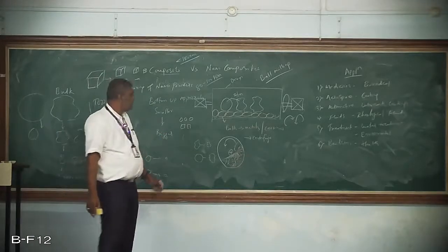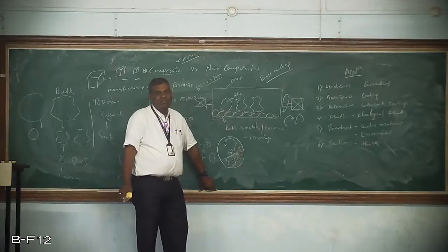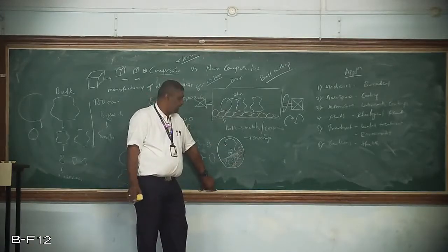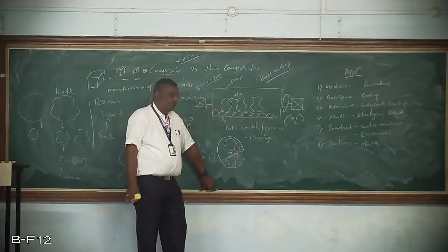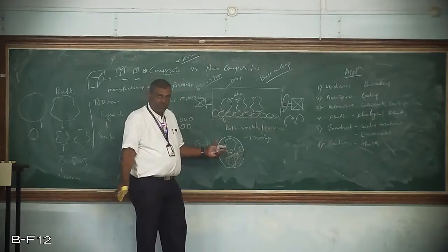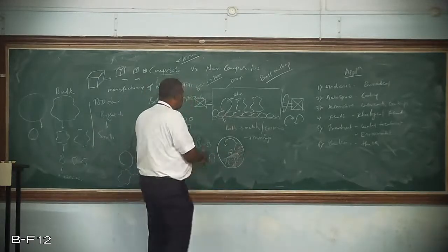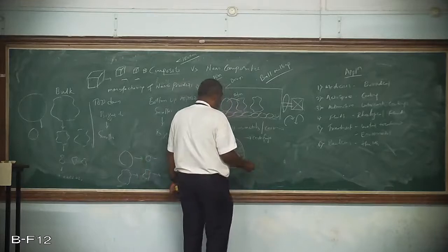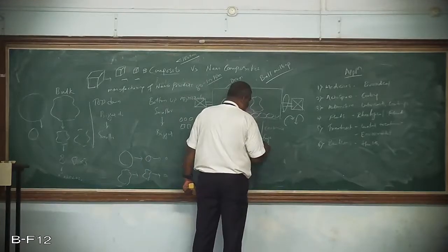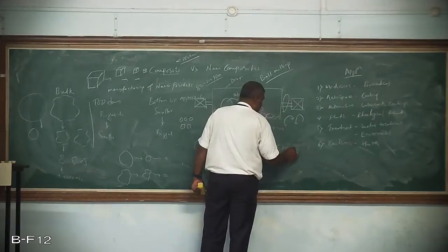Okay, so by this we can do the bulk sizing of nanomaterials, from bulk material to nano-size particles. If you want the bulk quantity, or more quantity, then ball milling is the only option. Here we can have variable parameters, like what ball size you can have and what speed it can rotate.